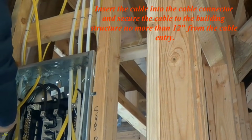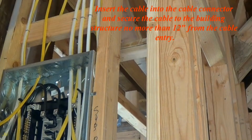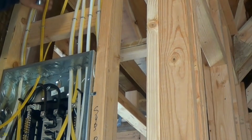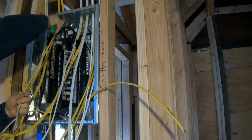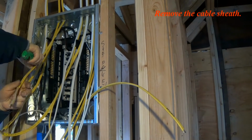Insert the cable into the cable connector and secure the cable to the building structure no more than 12 inches from the cable entry. Remove the cable sheath.